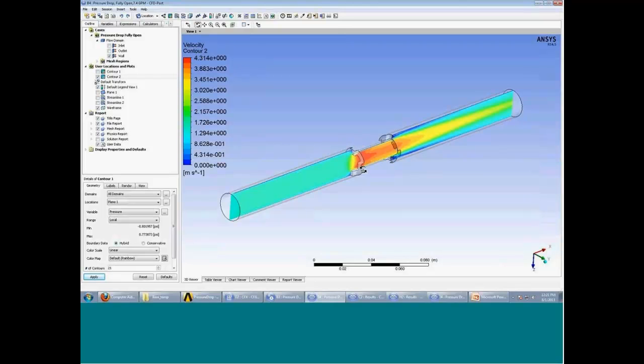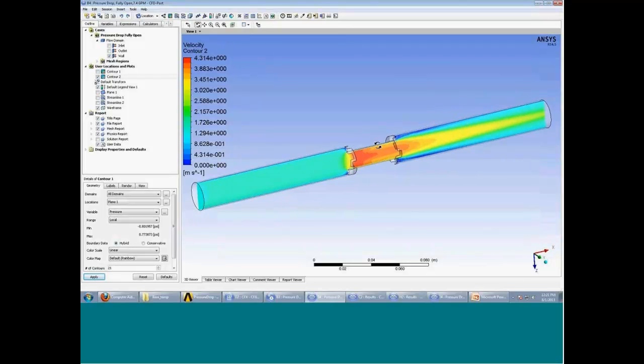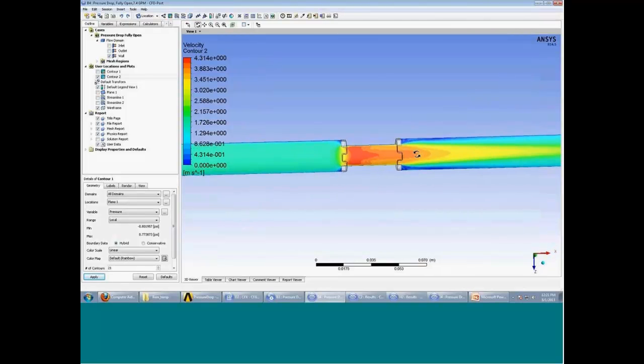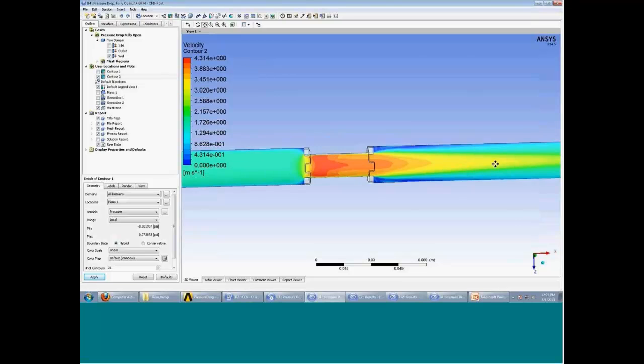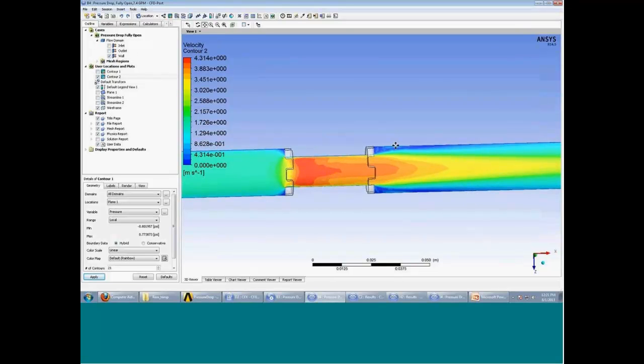You can take a look at the flow velocity, and you can see this is exactly what happens. The flow is actually accelerating in the valve region. As it is exiting, it's decelerating. Another thing to notice over here is that as the flow exits, you can see that there is a low velocity region at the top and the bottom of the pipe. Now, this is the region which corresponds to a small recirculation region which we are expecting to see due to the sudden expansion.